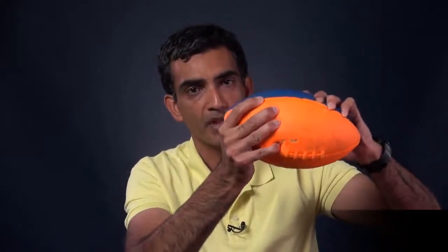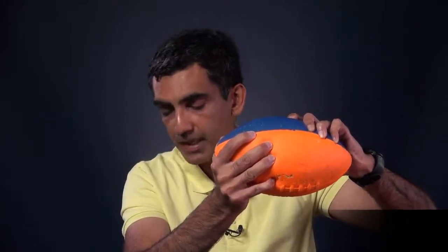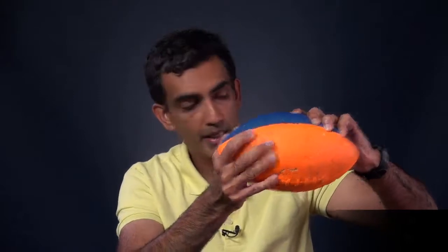Because this clearly means that as we deform the body throughout the material, we have a deformation gradient F at every point, and as a function of that deformation gradient we have this function psi, right? And just by definition, we are able to call this function psi the elastic strain energy density function.